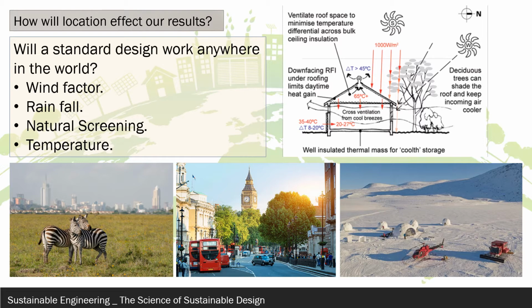If you look at the diagram on the far right hand corner of the screen, you'll see that a number of different factors are being pushed against that building, and the building has been designed to maximise the use of each of them. As you can see, the sun in the middle of the summer is bearing down directly onto the top of the building. Well, it's been given larger eaves to prevent the sun's rays shining directly into the windows, in turn reducing the internal temperatures within the building, which is not directly heated up through the glazing.